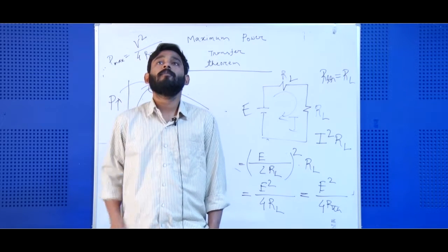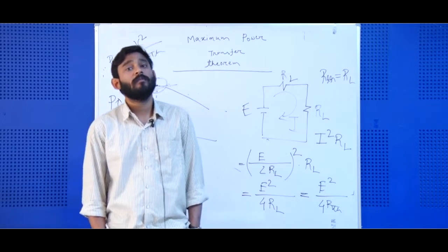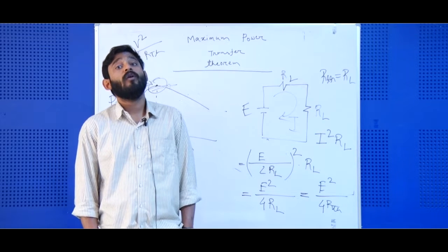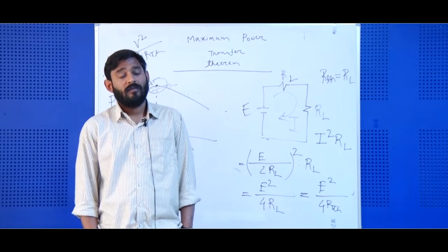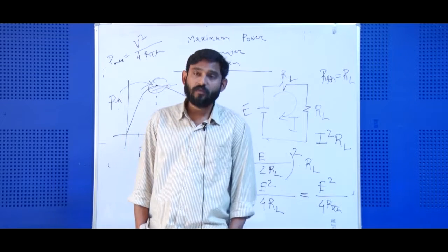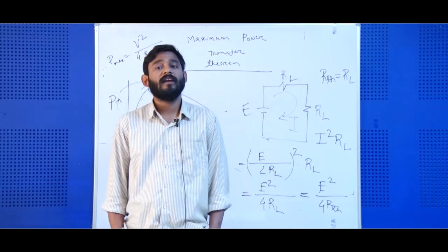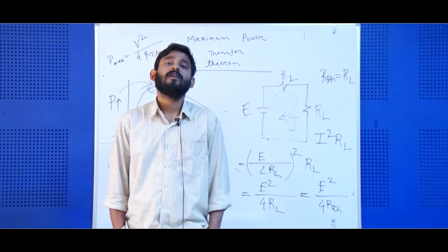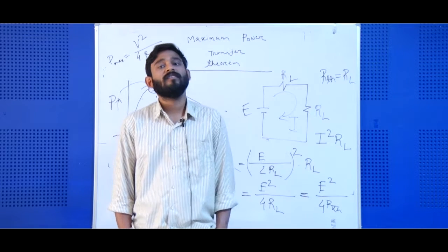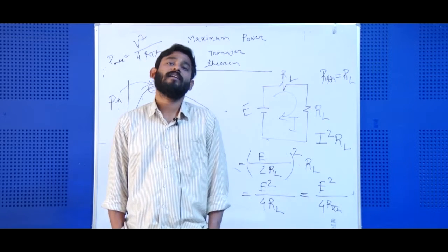Also, you will find the application of the maximum power transfer theorem in the tuning of antennas. The same thing happens when tuning an antenna. Basically, the user tries to match the impedances of the source and the antenna.